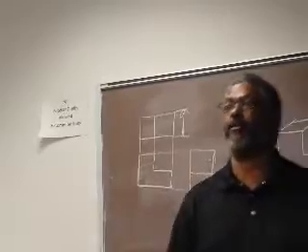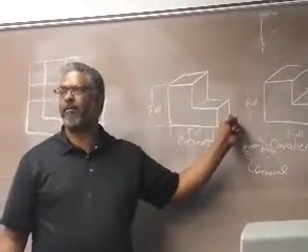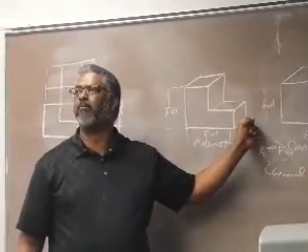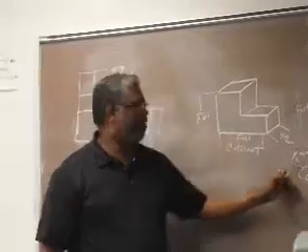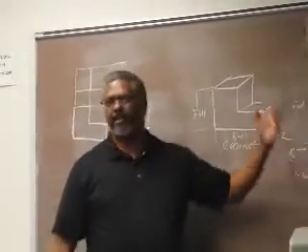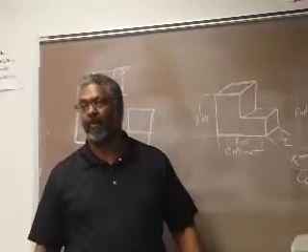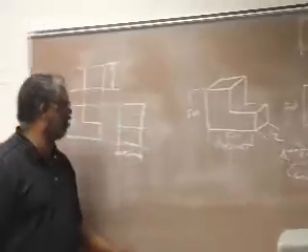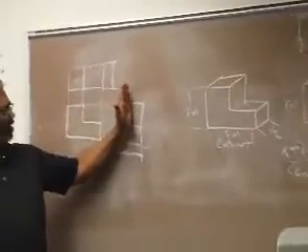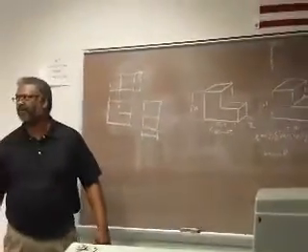To minimize that distortion, I could do a cabinet and it'll look more correct, or I could go 75%, and that would give me a general oblique. But whenever you do the depth, everything is cut in half, or by 75%, or whatever value you use.